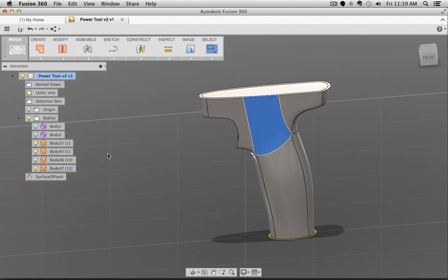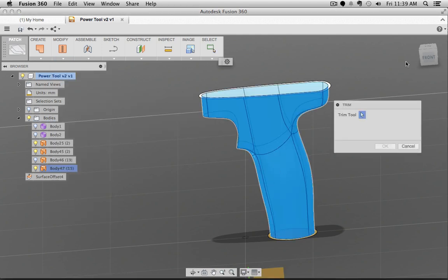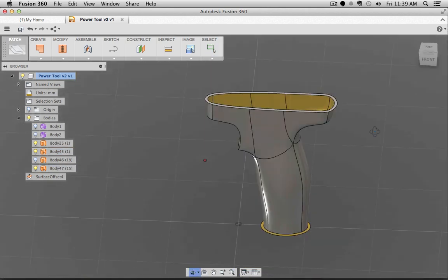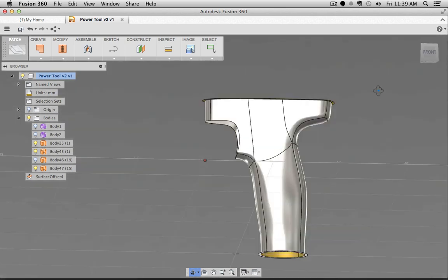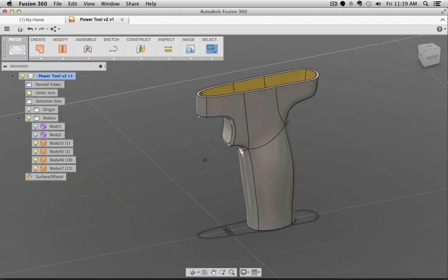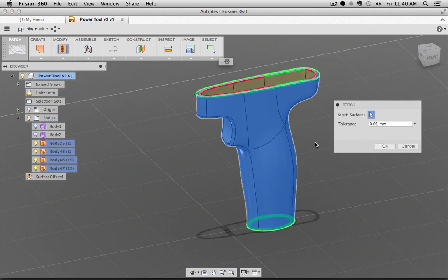And basically now I'm going to select the trim tool. This is my trim object. And I should be able, yep, to just select the insides, remove it. So you see, kind of like I have those bridge parts there. Show the other surface. Everything lines up now. And for example, now I can select everything and just stitch it. It will take probably a second to calculate.